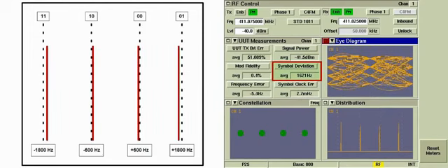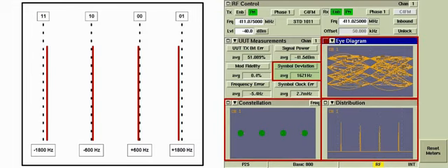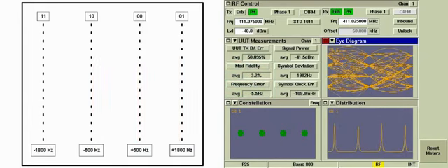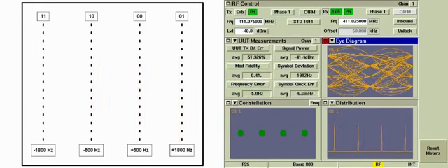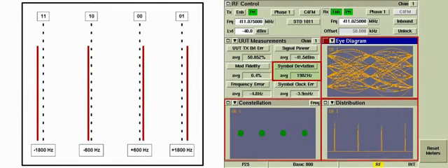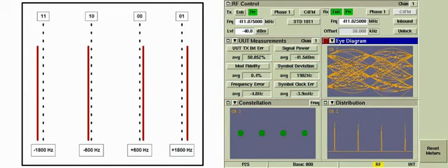The symbol deviation has dropped from 1800 Hz to around 1600 Hz. The symbol deviation meter and graphical displays reflect the low symbol deviation. The RMS deviation error and frequency error meters indicate those parameters are still quite good. The symbol deviation is now nearly 2 kHz. The symbol deviation meter and graphical displays reflect the high symbol deviation. Again, the RMS deviation error and frequency error meters indicate those parameters are well within the norm.